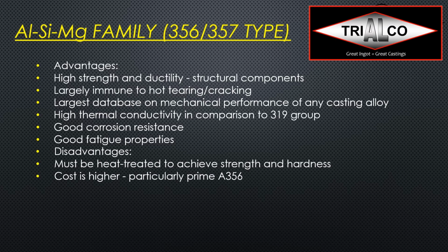Now, the disadvantages, of course, is it must be heat treated to achieve really high strength and hardness, which adds cost. And the cost is higher if we're looking at the primary A356 than, let's say, a secondary 319 or let alone a 380 alloy.